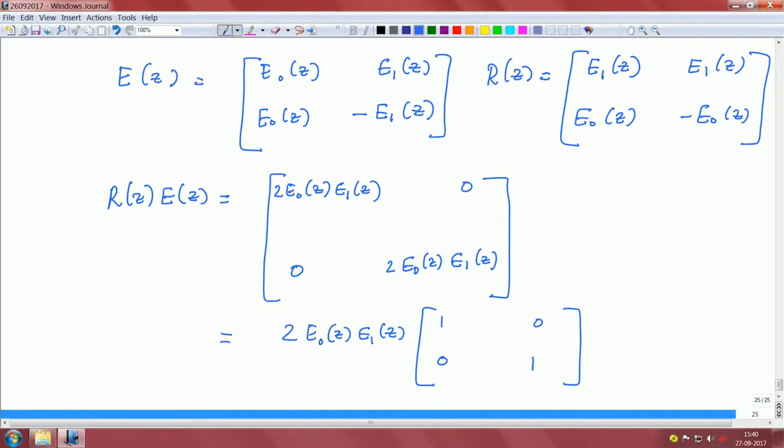So, if I do not force it to be identity, let me have the QMF imposition on this structure, this quadrature mirror property. Therefore, I can synthesize my analysis bank and synthesis bank, and I can come up with a polyphase representation, and from this I can simplify what R of z times E of z has to be, and that can be expressed in terms of the polyphase components.